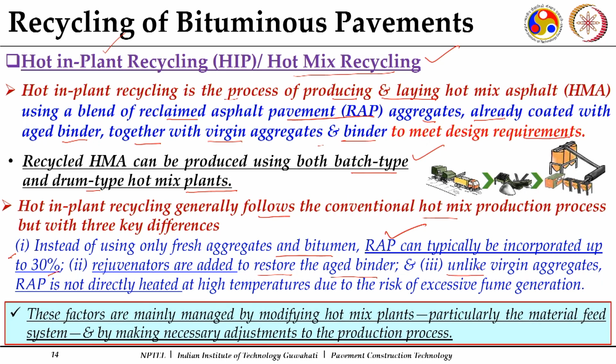And third is, unlike virgin aggregates, RAP is not directly heated. This is an important feature, because there is a binder which is already present, so it cannot be directly heated in the same manner as we do for the virgin aggregates. Otherwise, this binder will get further aged.